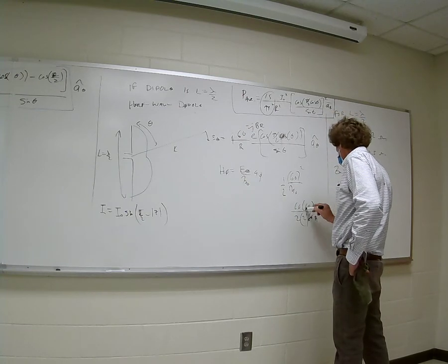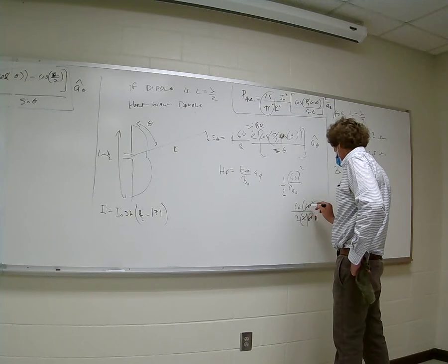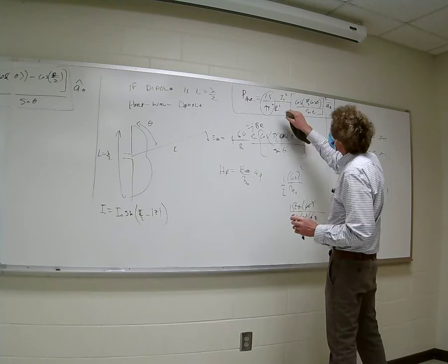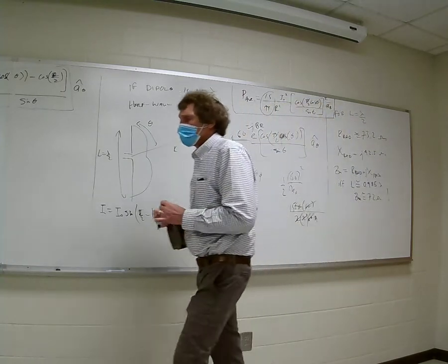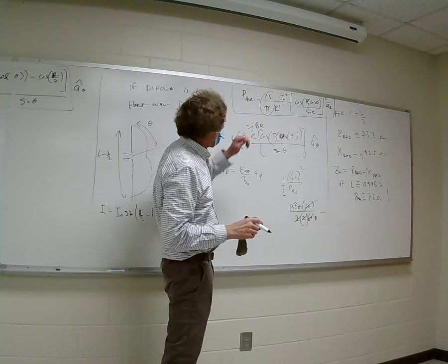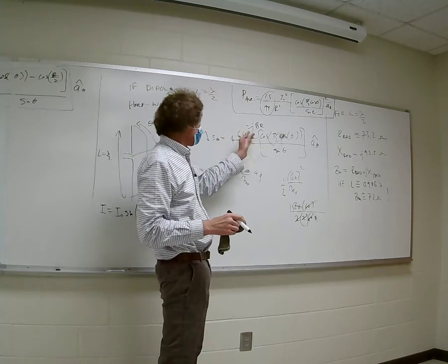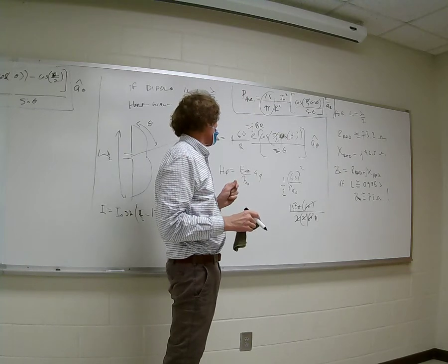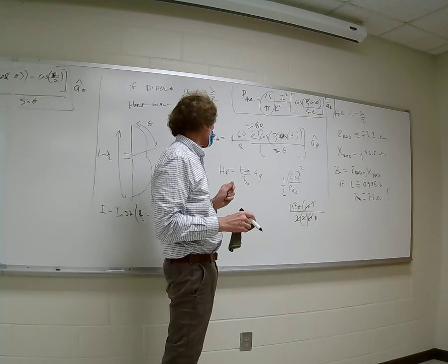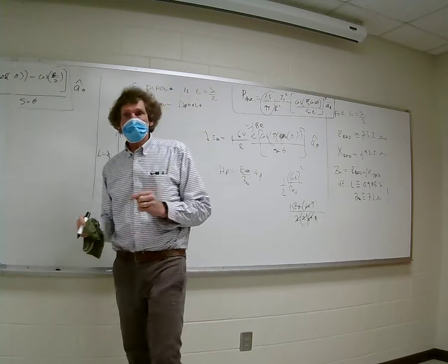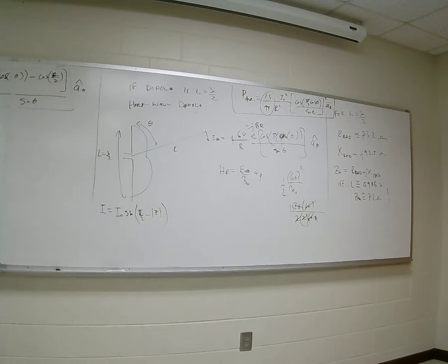That goes to 30, 15. Isn't this just 15 over pi r squared? That should be pi r squared. This is right, what I've got here. But the way you get it is just take the magnitude of E, which is 60 over r. So you get 60 squared over r squared, divided by 120 pi, multiplied by 1/2. You all follow me? I'm just taking 1/2 magnitude of E squared over eta.